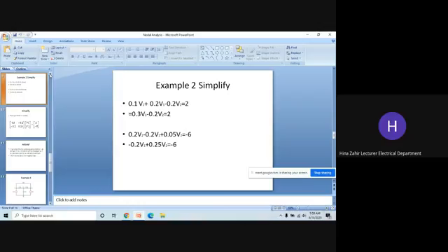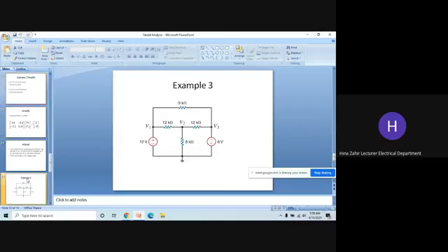But remember one thing, the best thing is that you will always assume all the currents are leaving the nodes and write those node equations. The difficulty is that sometimes the students get confused in, for example, V2 minus V1 by 12. This is the only difficult thing. And again, I'm giving you another trick: when you are writing the value of this current, go from V2 and at the end where another voltage is encountered, that is it. You would then subtract that voltage.